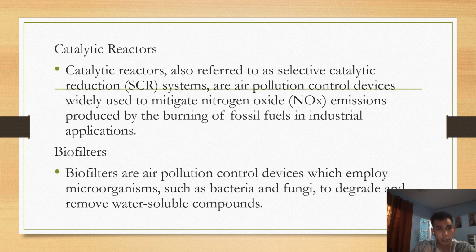However, the microorganisms in biofilters absorb and metabolize gaseous pollutants such as VOCs and organic HAP without generating byproducts typically produced through combustion such as NO and CO. These devices are capable of achieving over 98% efficiencies.